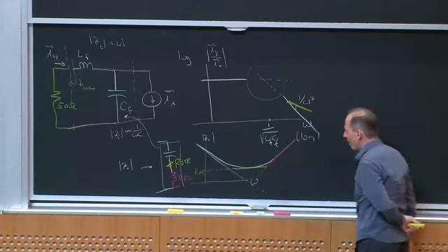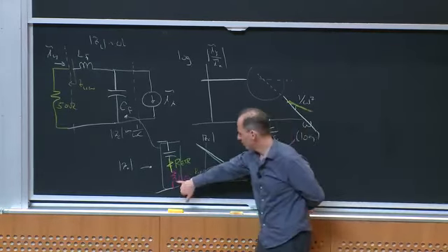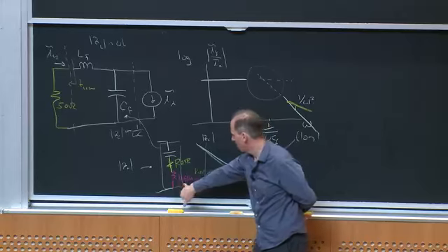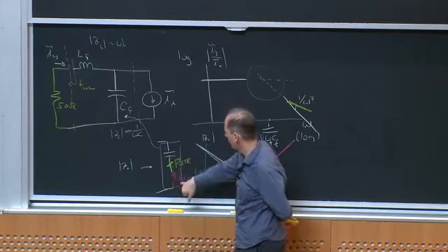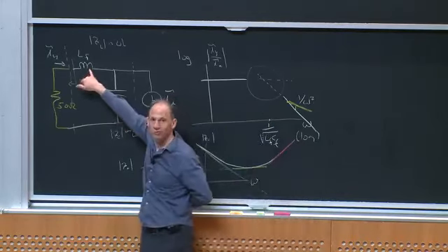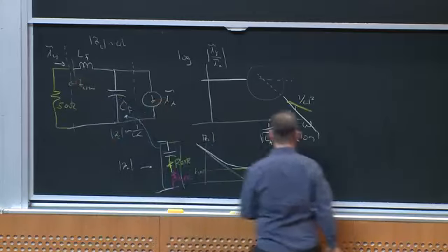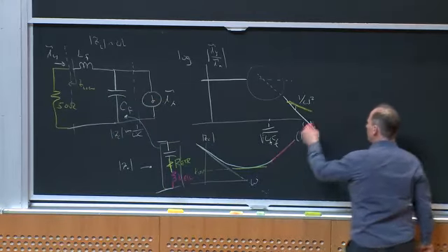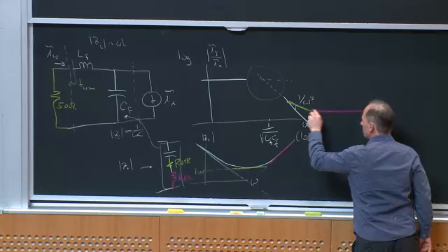And when I get to really high frequencies, ESL is going to dominate, and then I'm just going to have a current divider between L_ESL and L filter, right? And in fact, what that's going to mean is my attenuation is just going to flatten out, right?